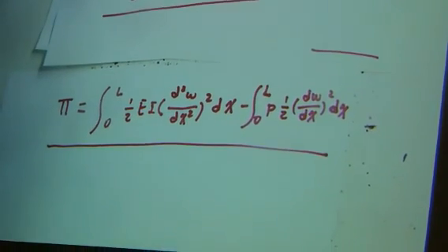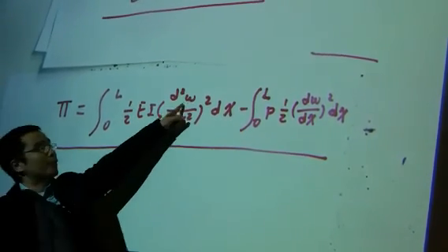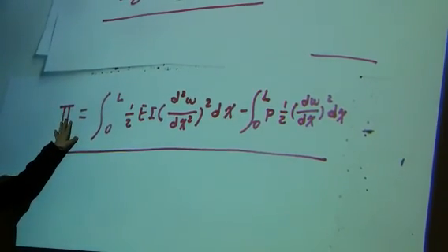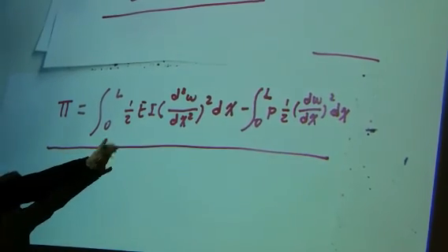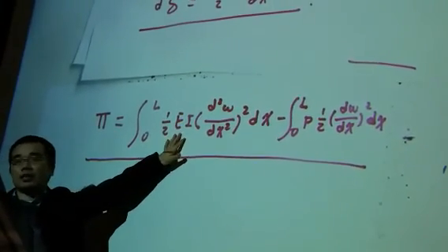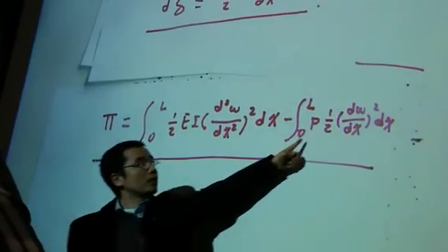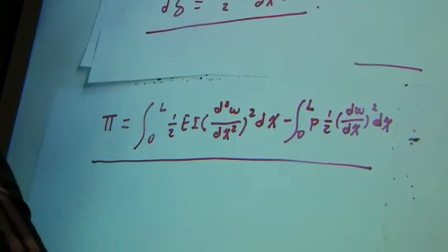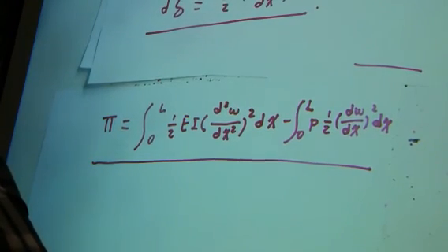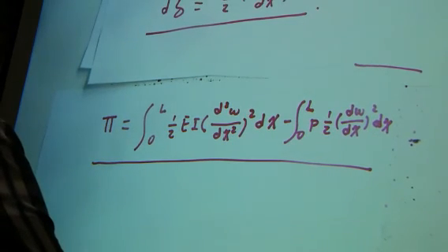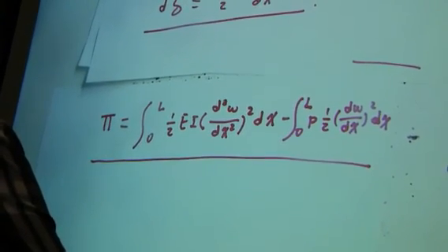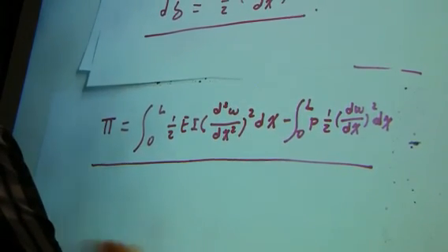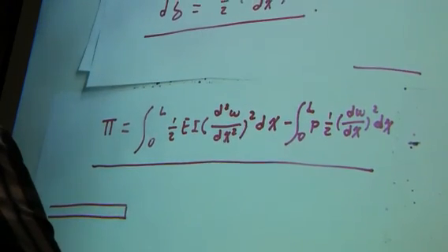When you apply a compressive loading, you will have deflection w. So this energy is in terms of w only now. Right? Only unknown. All of the other things are known: Young's modulus, sectional property, driven loading. The only unknown is w. So according to the energy principle, this structure is in equilibrium, and the energy has to be minimized. We follow the same principle as when we derived the stiffness matrix. Okay? So this pi has to be minimized. And then we come back to solve for this.